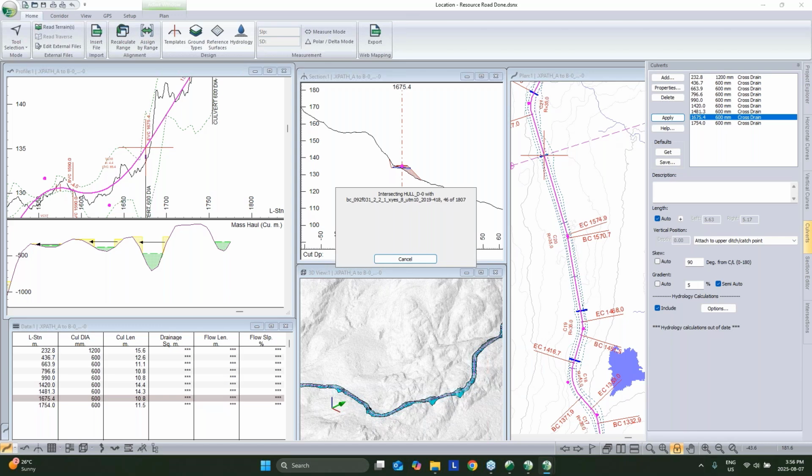So doing a quick recalculation. And this is actually going through and stitching that road surface in with your topo surface. And yeah, we can quickly add the pipes in and calculate our drainage area as we go for those.